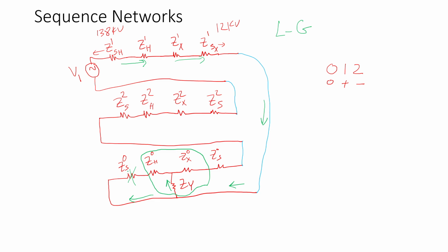So if you remove this here, that means most of the current will flow through here because you basically reduce the impedance. So you are just saying most current will flow through here. What that would do is cause the stabilizing winding to be undersized, which is a problem. So having the T model and also the system impedances in place is very critical.